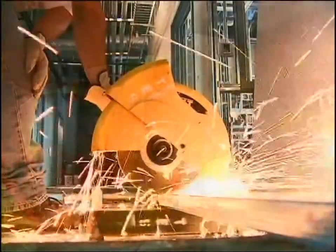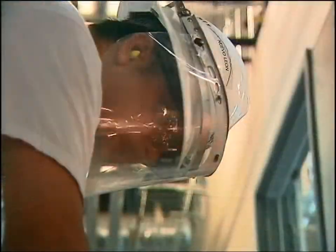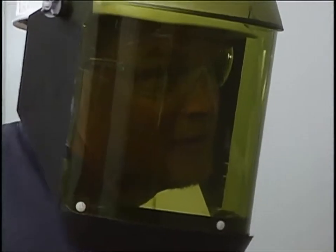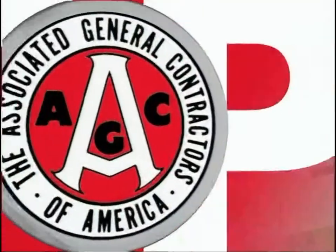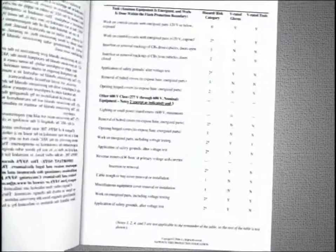In some cases, such as when grinding or cutting with an abrasive cutting wheel, you will be required to wear safety glasses and a face shield. Wear safety glasses or face shields when exposed to any electrical hazards, including work on energized electrical systems. Be sure to consult the applicable National Fire Protection Association 70E tables for the appropriate protective equipment for these hazards.